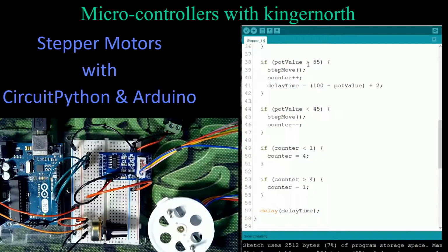So it's going to take that value that I just created up here, up on rung 41 for the clockwise direction. It's going to take that value and write it into here, and that's how much it's going to slow down the program by. It's a pretty small delay, but it'll be noticeable when we get into getting fine control. Well, we need to put a similar formula in for counterclockwise.